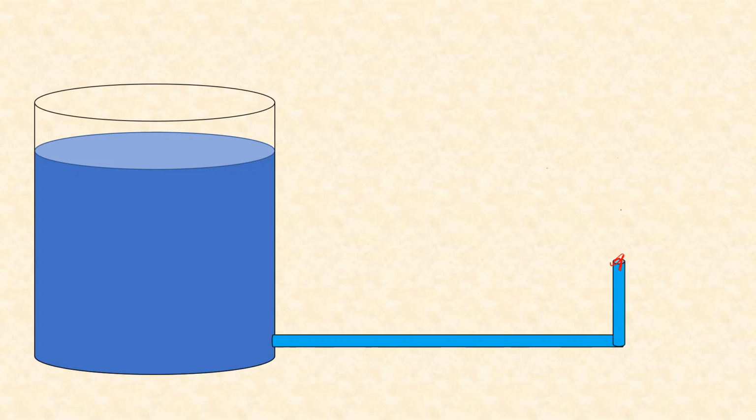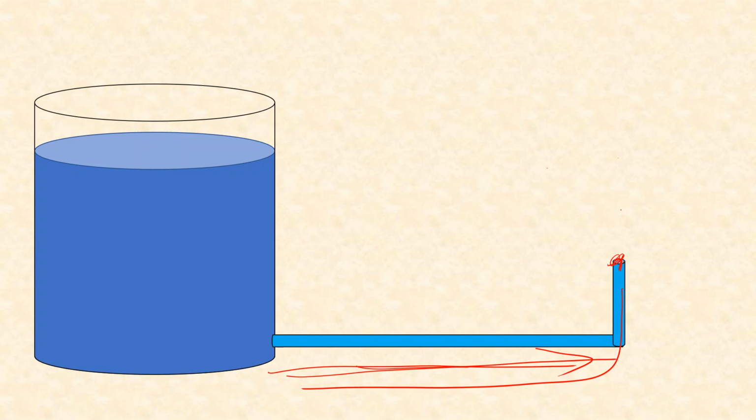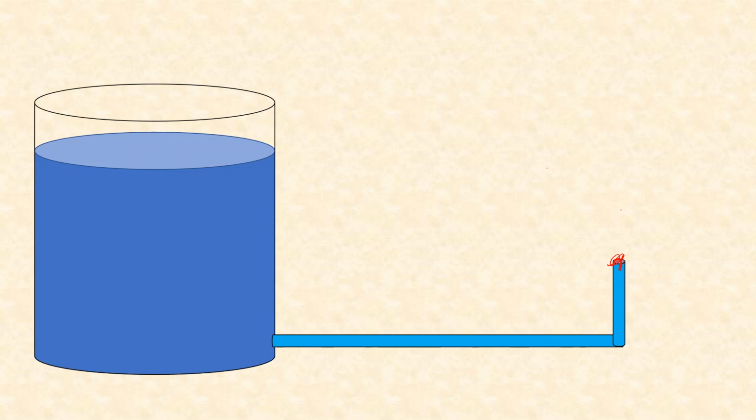if you are blocking this pipe, you are affecting the whole flow, and the entire velocity inside this pipe will be decreasing. And therefore the head, since we have found from the whole equations that the head loss is a function of velocity. As velocity increases, head loss increases. But if you decrease the velocity inside the pipe, the head loss will also be decreased. Once you block this pipe, maybe using your finger or maybe by closing a valve here and so on, that way you are actually decreasing the velocity inside this pipe and therefore decreasing the head loss.